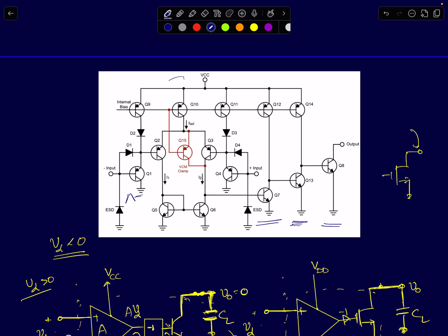If you recognize this, this is a bipolar junction transistor based comparator. The first stage is a PNP common emitter differential to single-ended amplifier, followed by two common emitter amplifiers. The second two stages are common emitter amplifiers with current source loads. These are all current mirrors with some bias voltage, so they act like current source loads and give you the highest gain possible in each stage. The gain of each stage will be close to the intrinsic gain of this technology.